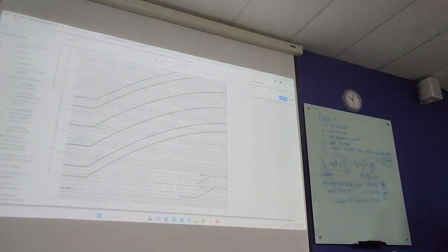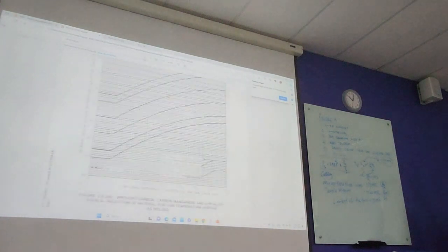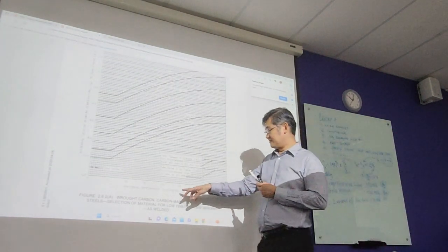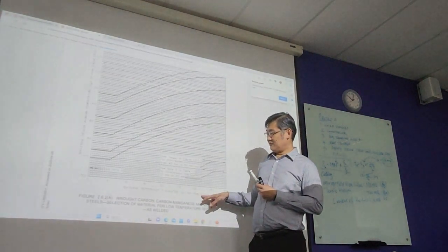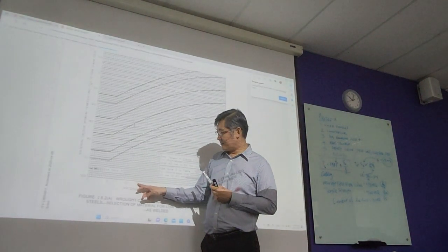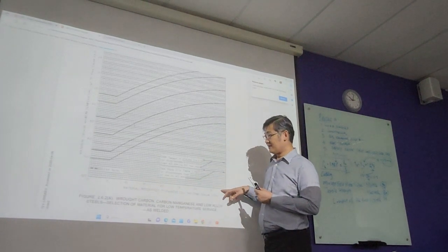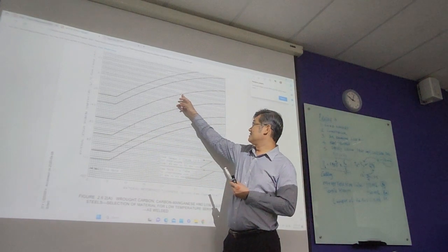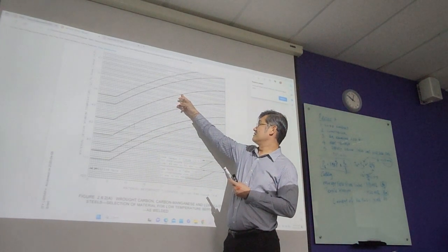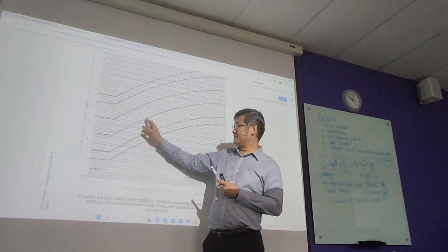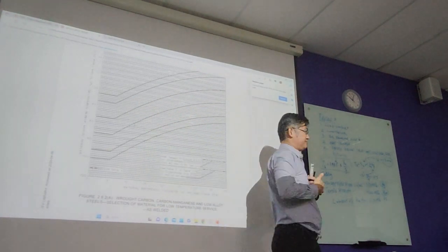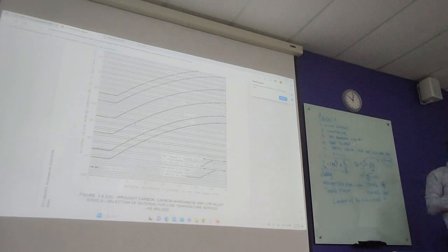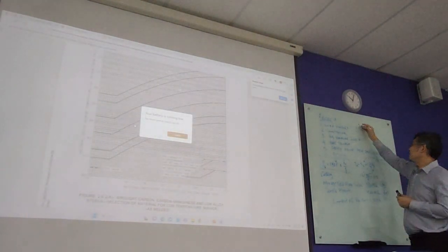Okay, so this is why I mentioned to you just now. This is how we determine the thickness. We use 13 as a reference point because this is our TR one. So 13, you draw a line. We use the 0 degree curve over here, then you will find your minimum material design minimum temperature. They call this MD.